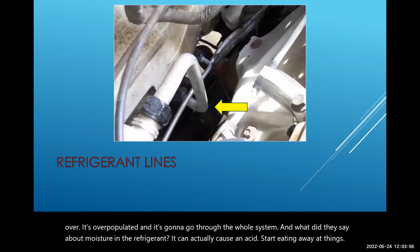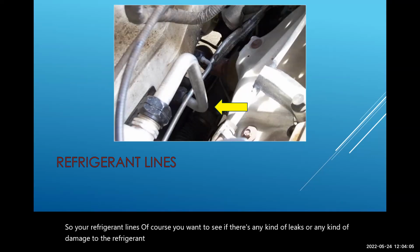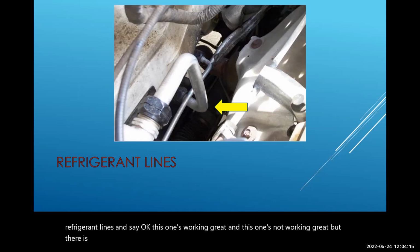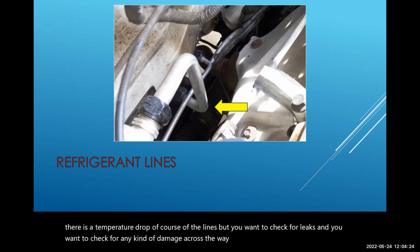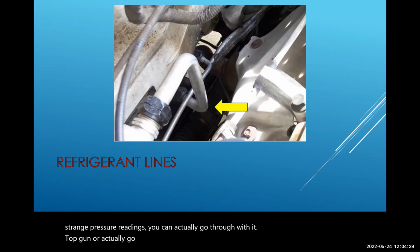So for your refrigerant lines, of course, you want to see if there's any kind of leaks or damage to the refrigerant lines. My dad used to do this too. He used to just touch the refrigerant lines and say, okay, this one's working great and this one's not working great. There is a temperature drop across the lines, but you want to check for leaks and for any kind of damage along the way. If you start getting some strange pressure readings, you can go through with a temp gun or touch the lines. You can actually identify if there's a plugged-up section along the way too.